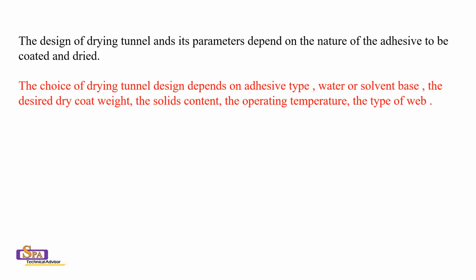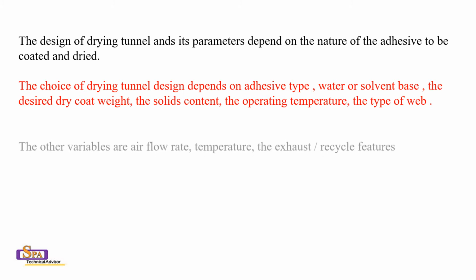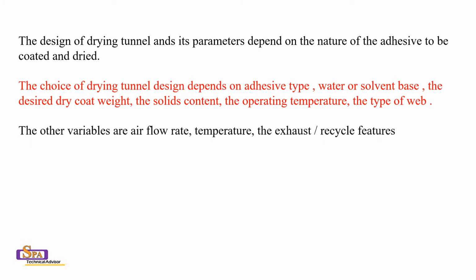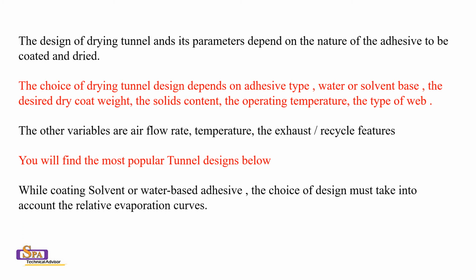The choice of drying tunnel design depends on adhesive tape, water or solvent base, the desired dry coat weight, the solids content, the operating temperature, the type of web. The other variables are airflow rate, temperature, the exhaust or recycle features. You will find the most popular tunnel designs below.